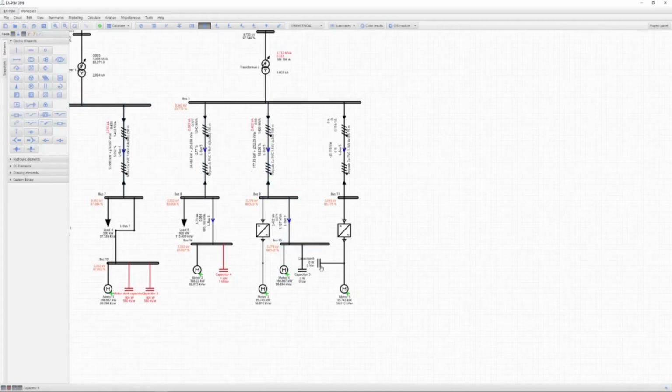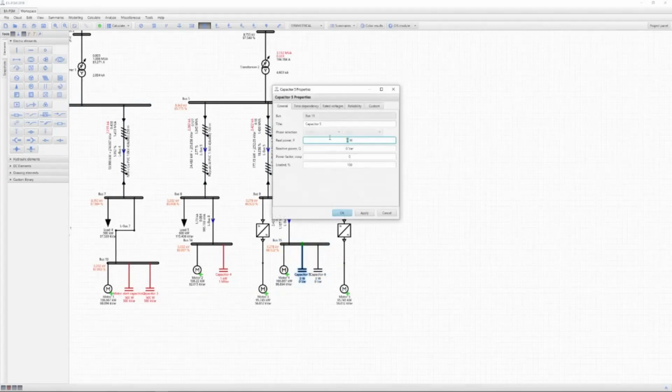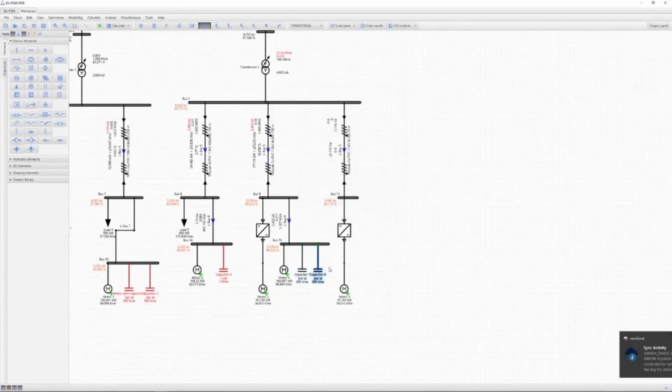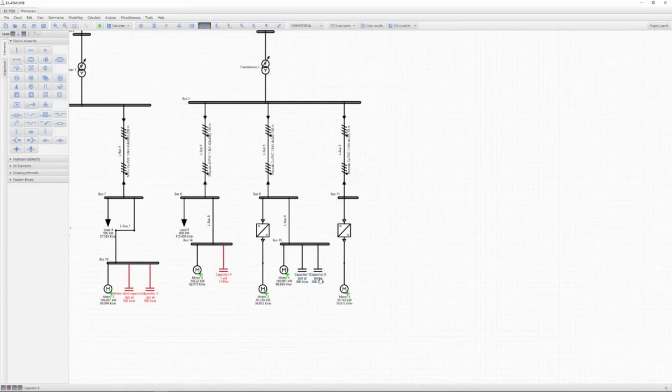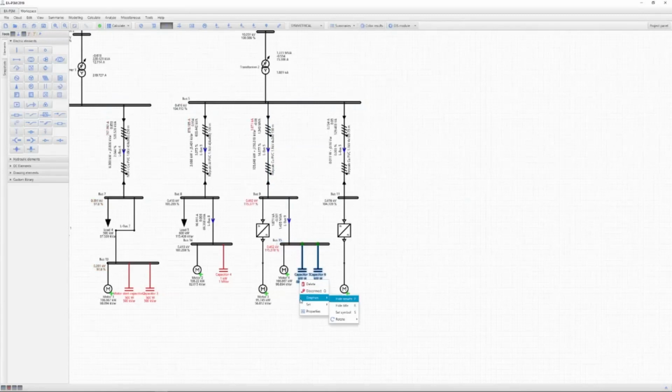So now let's add two capacitor banks that are 600 kilowatts. And now we're gonna check again. As we can see, we have compensated here again, and now the transformer is not overloaded. But now we must check if the capacitor banks are connected when we do power flows. Yes, as we can see, the voltage increases. That is why we must disconnect them, but only connect them when the motor starts.